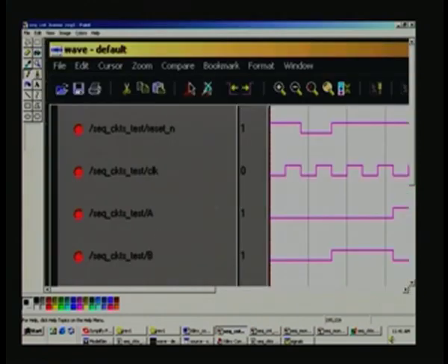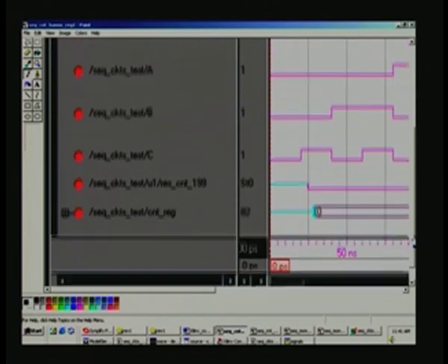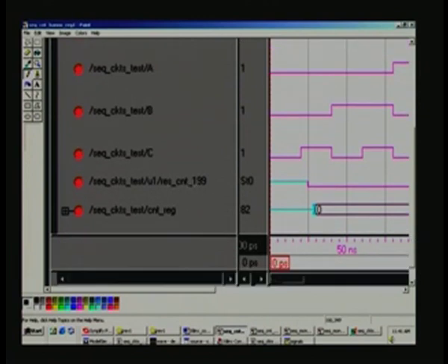So, you can see reset, clock, ABC as input here, and finally a reset count. Here you can see that after back annotation, I could not find reset count as well as advance count. Advance count is totally missing. As I mentioned, it was used in other circuits. So, naturally that got dropped, because a similar signal was there under some other name. So, at the time of optimization after synthesis itself, it was missing advance count, and here also it is not to be found after back annotation.